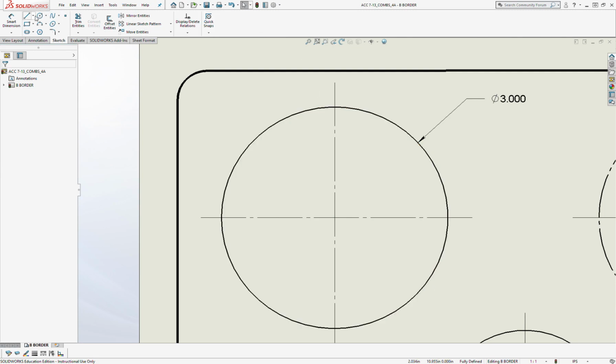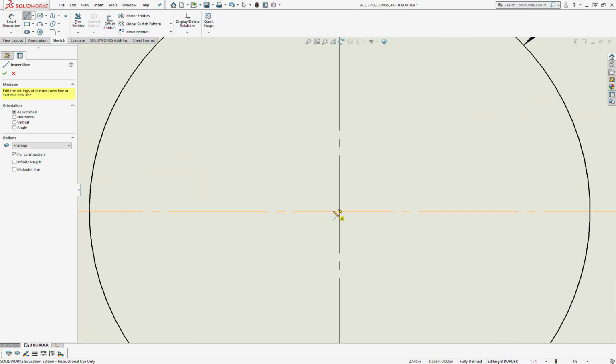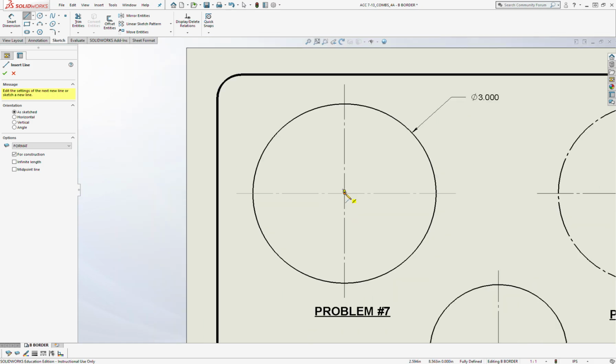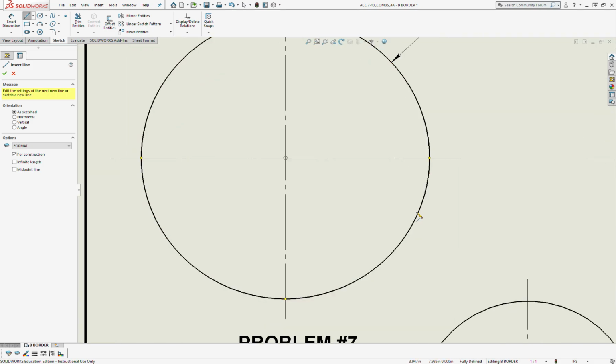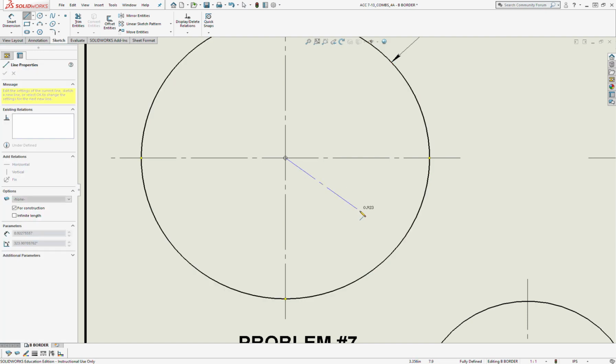I'm now going to go here and drop this down, the line tool to center line. I'm now going to connect it to the center, and this is important. Don't get caught at a midpoint of one of these 2 lines. Okay, make sure you are at the center. Now, if you're not sure of that, hover on the circle, and you'll notice a round circle shows up. When I see that, I'm going to left click on it, pull down until I touch the edge, left click,